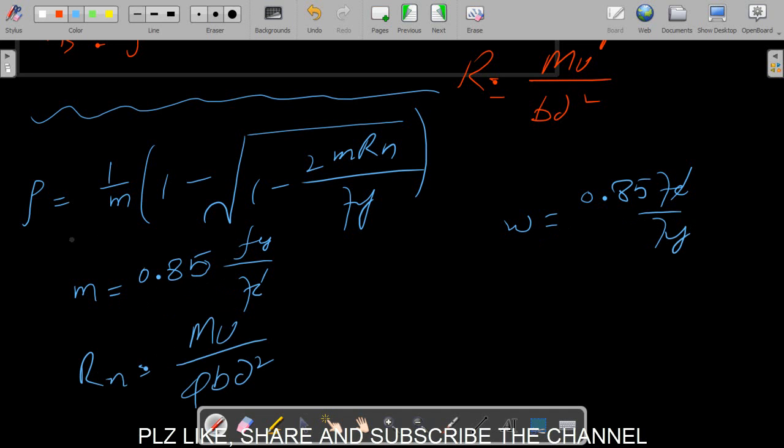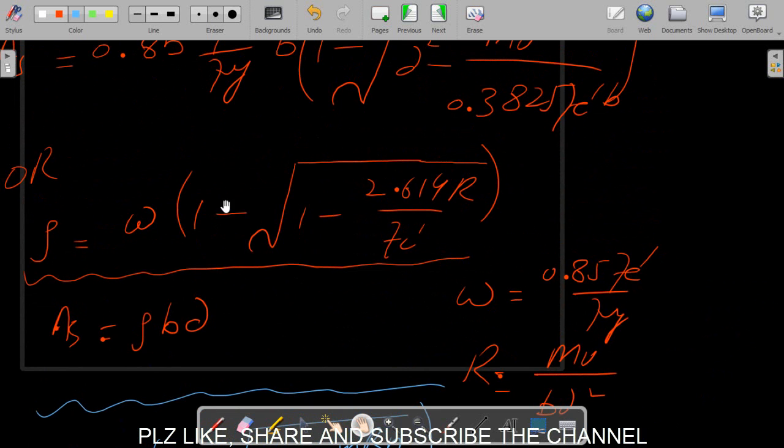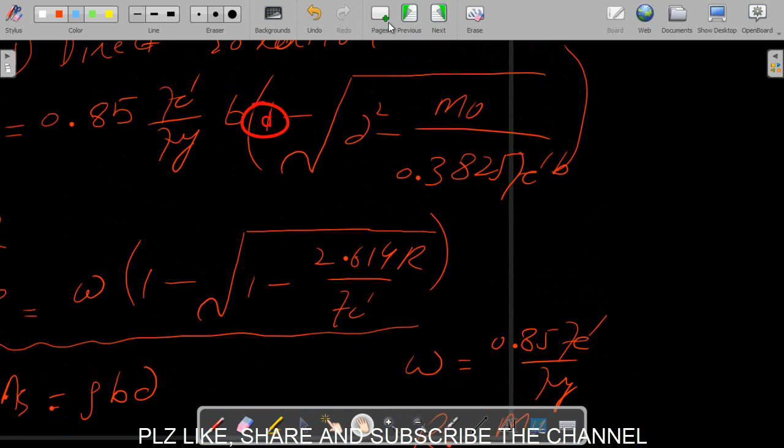So we will use this equation also sometimes. This is also a direct method. We can use either this equation or that equation. And finally we find the area of steel by using rho, the steel ratio, times BD. So this is all about the direct method.